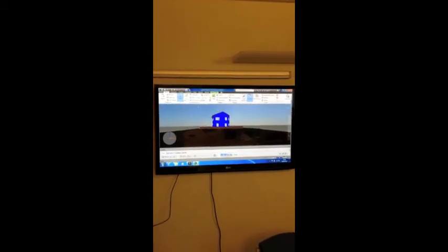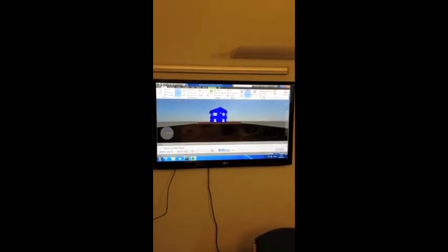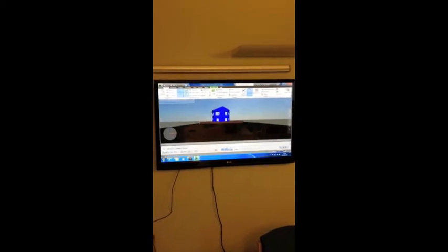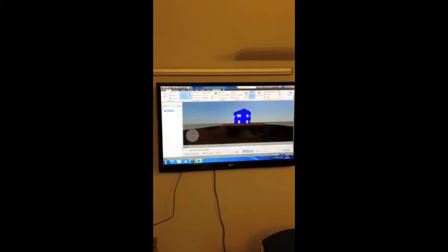The alternative way of doing this is to click Select Same and either select same name or select same type. For this purpose, for the external walls, we're going to use select same type. And that has selected all the external walls within the house model. You then click Save Selection, and you can name this selection set as you wish. So we'll call this External Walls.